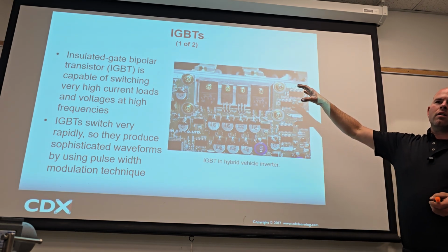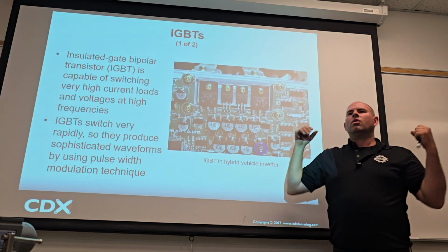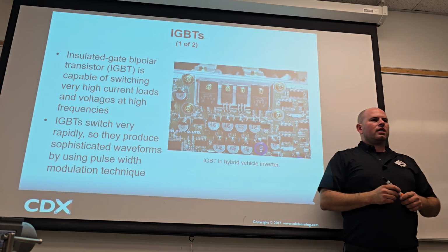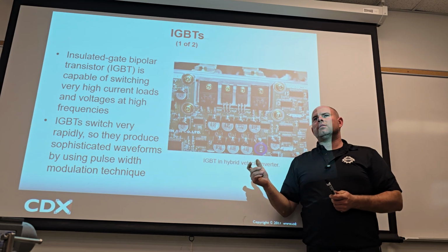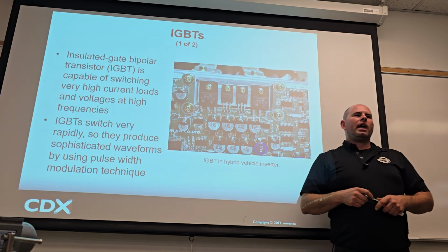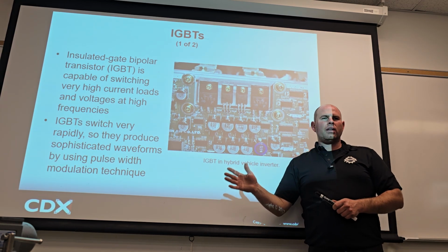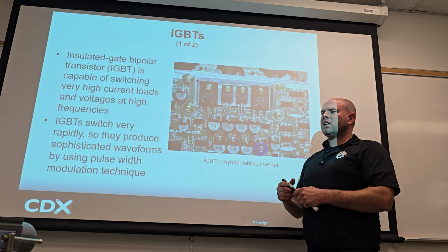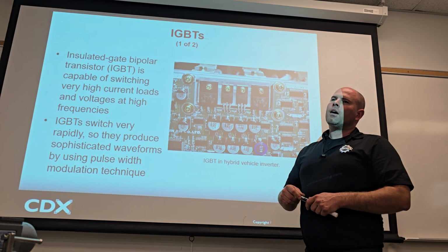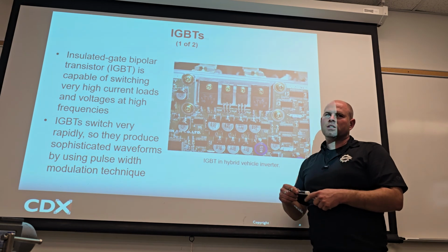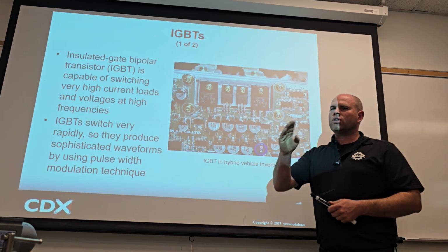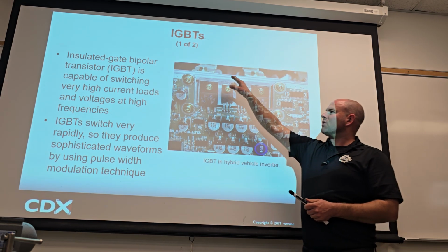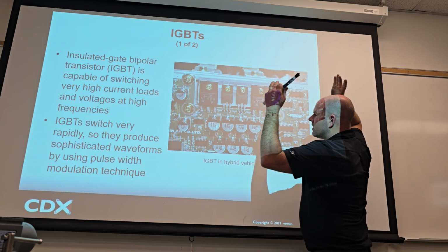You'd go at it like, zoom out. What's the customer's concern? Let's say it's a hybrid vehicle and it won't move and you have a hybrid warning light on. You go in, you check codes, and it says something along the lines of loss of isolation inside the inverter.